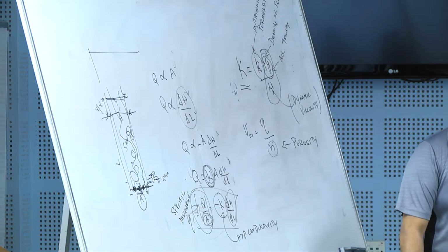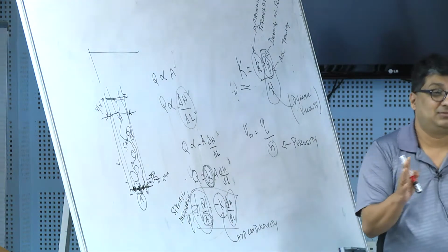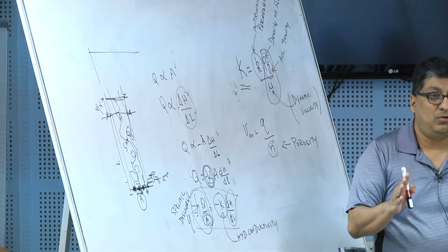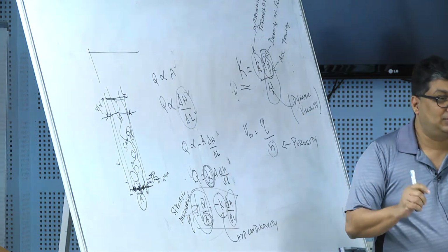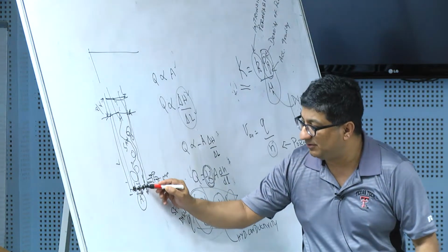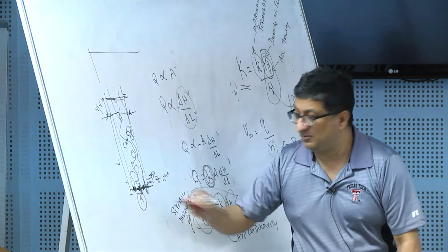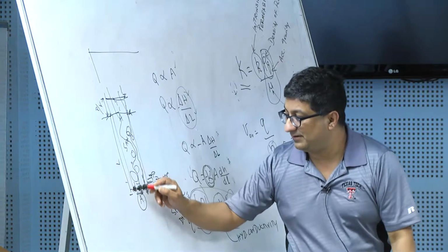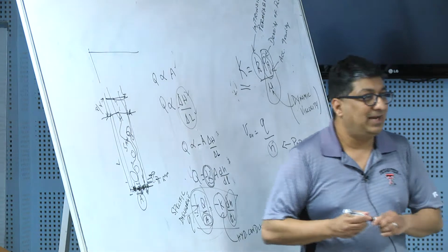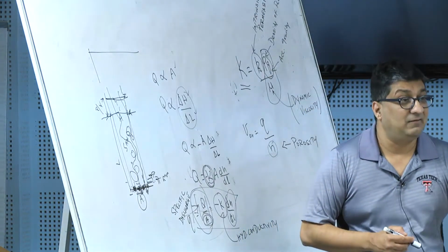Now there's another kicker, right? We have pores, and we just said that even in a simple sand column of Henry Darcy, the pores have different sizes. Which means if I look at the velocity of this flow path, it will have one velocity. If I look at velocity in another flow path, it's going to have another velocity. If I look at another pore, it will have another velocity. So that is what's called pore water velocity. That is the velocity at an individual pore.